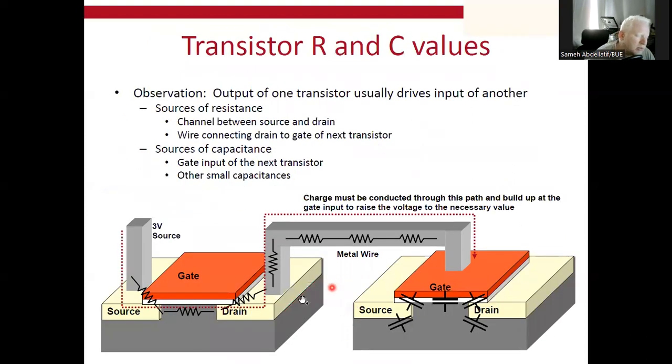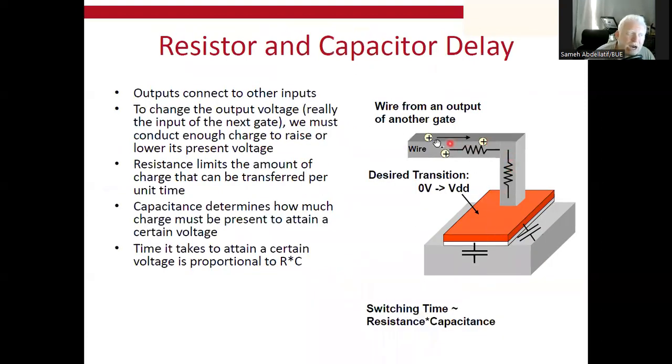So when we connect MOSFETs together, for example, to build an inverter, which is the simplest logic gate we studied one lecture ago, these connections add a resistance in addition to the capacitance. From this perspective, the RC perspective starts to appear in CMOS technology. So we have a capacitance due to the MOSFET, and we have a resistance due to the connection or the path connecting different MOSFETs in a chip.